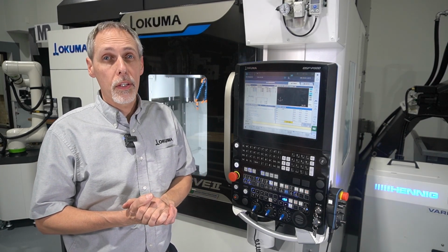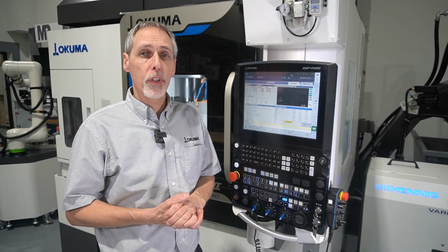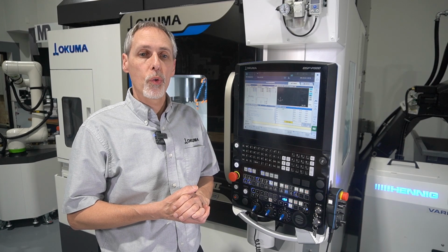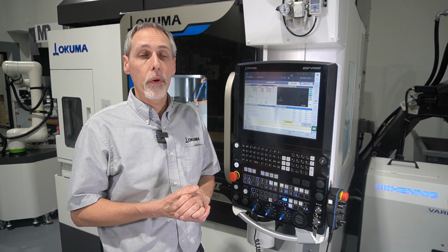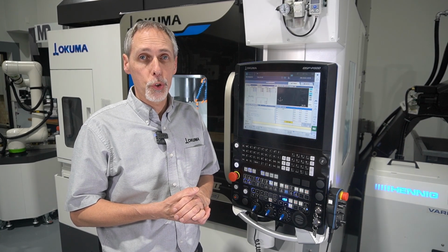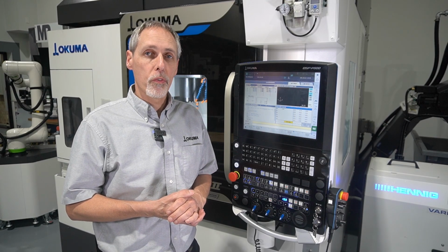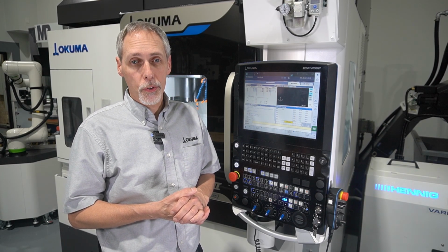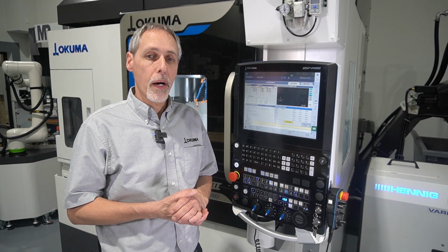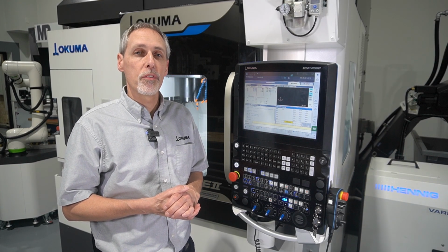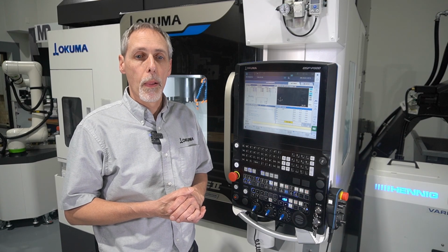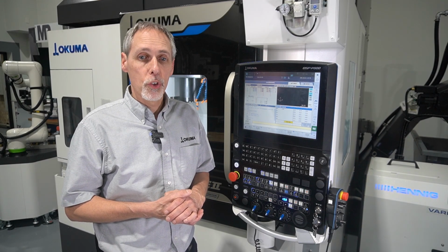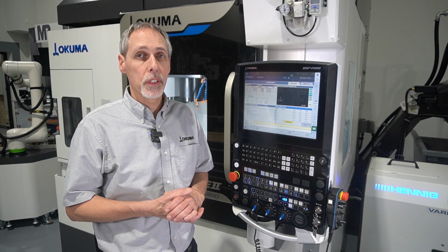So, what is Tool Life Management? Well, it's a function where the control counts the time that's used for cutting, or the number of work pieces, or the travel distance for any particular tool. So that total value is then compared to the limits that you set for that particular tool. And once the life is expired, the management function checks to see if you have defined a spare tool or not. If there is a spare tool, then it's automatically changed to that tool. If there's no spare, then you're going to get an alarm and the machine's going to stop running.